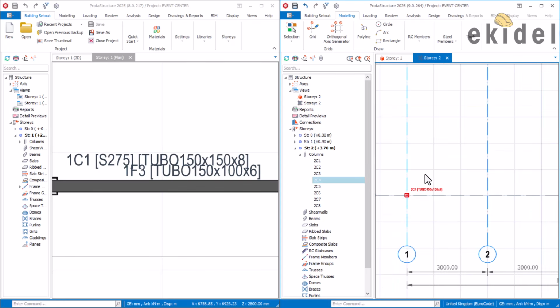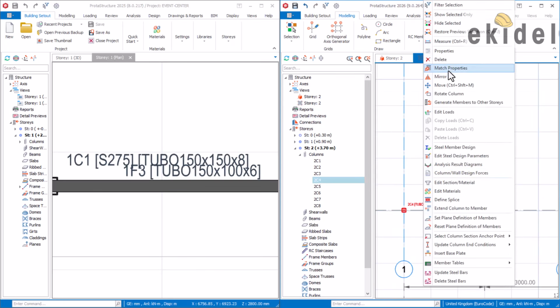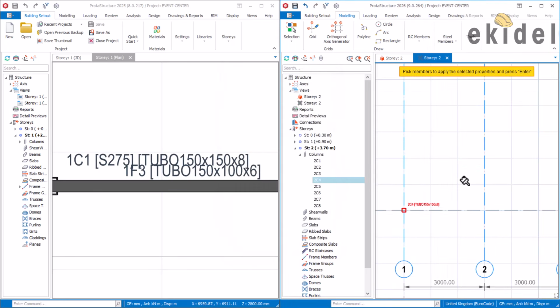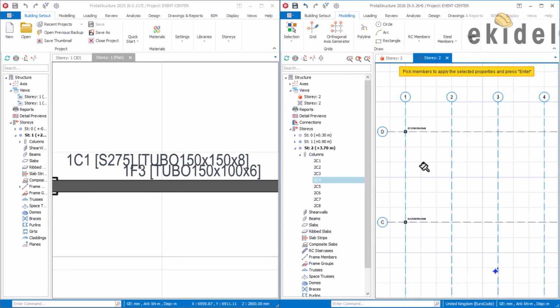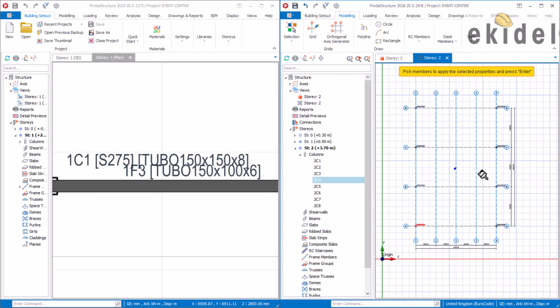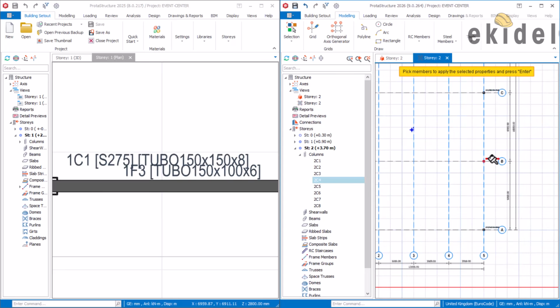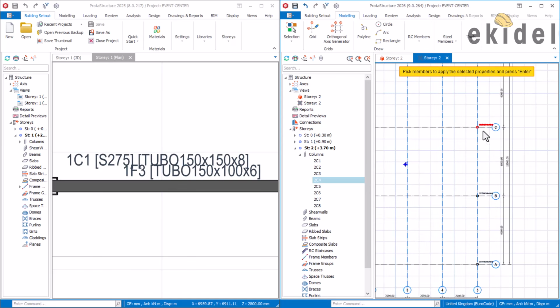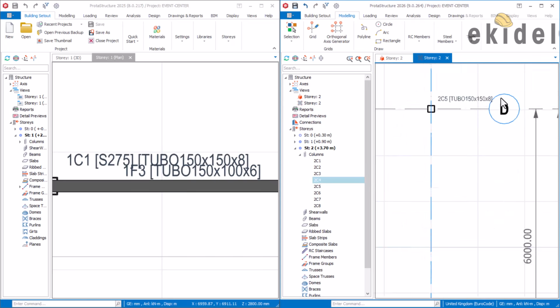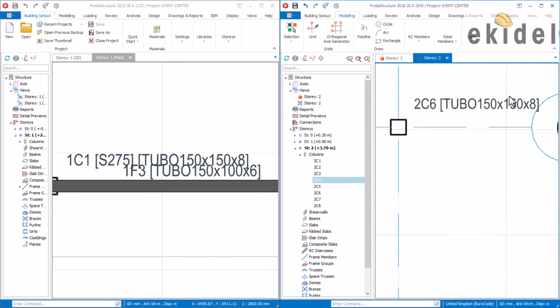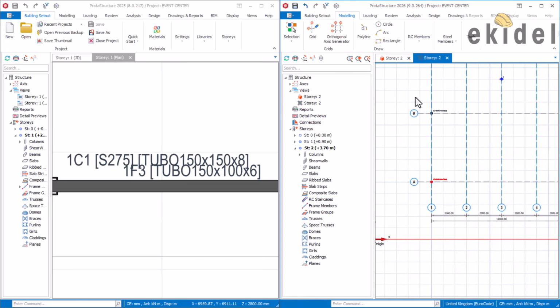In that note, we click on this and say match property of this particular one, say yes match, and again we are going to highlight all this by doing something like this. Then you click on this, this, this, and this. Once I'm done clicking, just press enter, and everything will change to that value. Can you see that? It has changed now, correct? Everything has now changed to the exact section size, which you can see here.